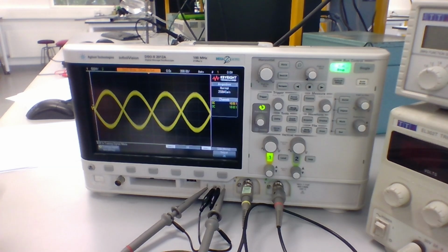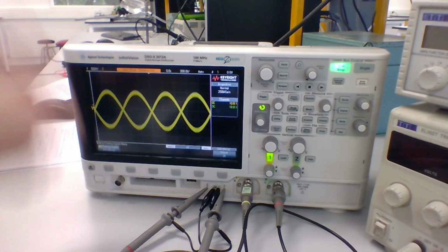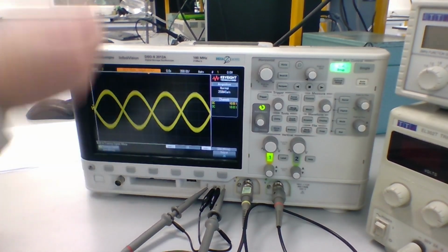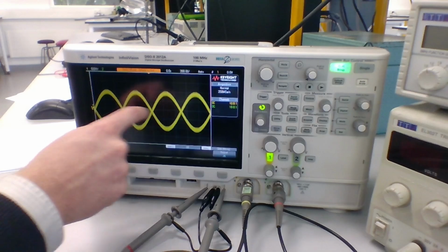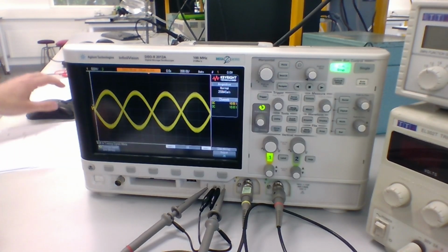Okay, so we're currently measuring the signal. As we can see, we get this weird, glitchy looking, duplicated, noisy thing. The problem is that this is a single sine wave, like we had in the previous lab. But because it has noise on it, it keeps going up and down, up and down, and it keeps crossing the trigger again and again. And so in auto triggering mode, this means the oscilloscope keeps taking measurements at weird timings, and we end up getting this duplication of the signal on screen.